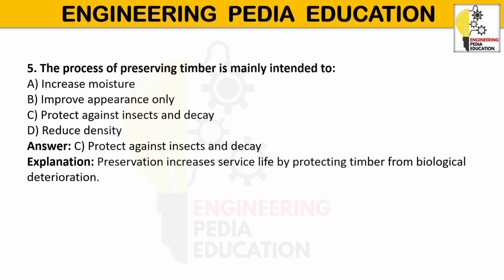Preservation of timber is the process of protecting wood from decay, fungi, termites, insects and weathering by using suitable treatment or chemical. Even though timber is a strong natural material, it can deteriorate over time if it is exposed to moisture and biological attack. Proper preservation increases service life and reliability. Why is timber preserved? Protect against termites, wood boring insects, prevent fungal decay and rotting, increase durability and lifespan, reduce maintenance and replacement cost, improve performance in outdoor and damp conditions.